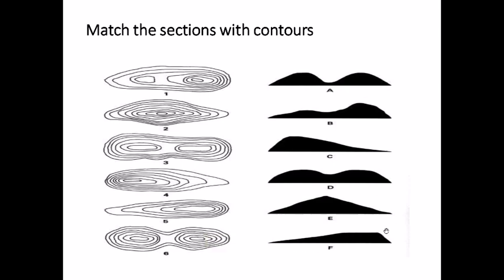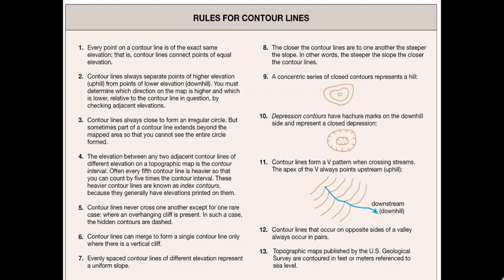So you have on this side a flatter surface, that's why a bigger loop, and the slope is steeper over here. So the contour lines are very close on this side, and the slope is very mild over here. That is why the distance between the contour lines is bigger on this side. This is how you decide, or you can get a picture by looking at these maps, what sort of a land we are talking about. So you can do the rest of them and follow the same principles.